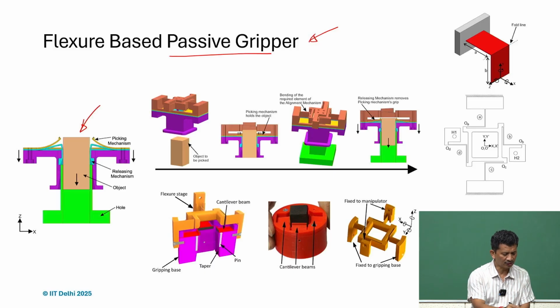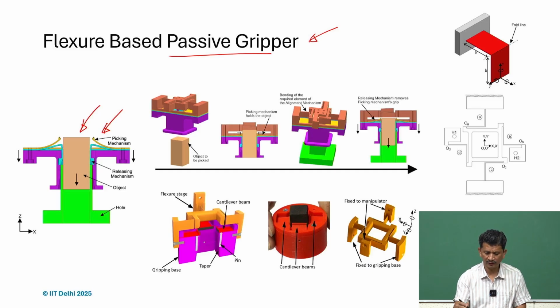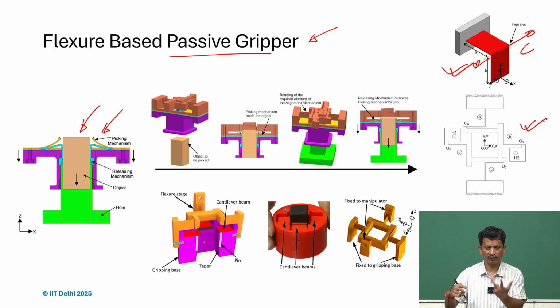And you can see there are a lot of compliant parts here, and we can go in the detail. The functional part is this folded sheet flexures, and what we understand is that this is the constraint direction, the fold line, and we use that concept, and we have these configurations in series, and then we are able to get that.